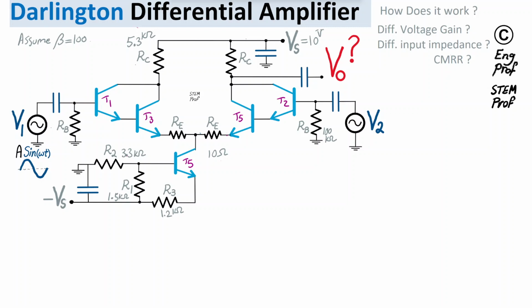For the differential voltage, let's say V1 is applied like this, and let's name this, for example, plus V over 2. And then for V2 in differential mode, we are effectively doing exactly negative V over 2. So when that signal is increasing sinusoidally, we are decreasing at the V2 side. What that means is, while we have mirror symmetric DC currents flowing through these branches, these are DC bias currents. Those are, let's say, sizable currents.